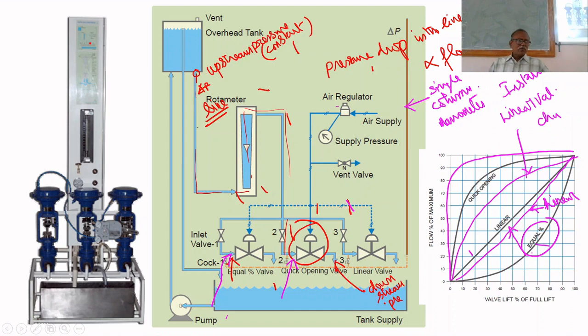You know the U-tube manometer, a double column manometer. In a single column manometer, only one column will be there, and the other end will be connected to the pressure end. So this single column manometer's other end is connected to where we have to measure pressure, just before the valve.